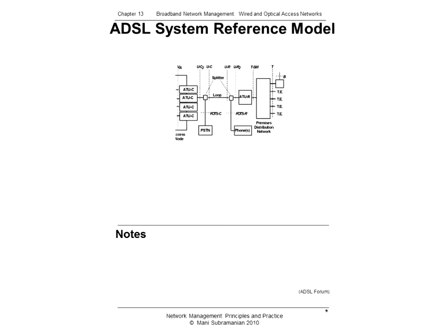Now this figure shows the ADSL system reference model. Here we have additional components that we call splitters at the central office and the customer premises, which separate low frequency telephony from voice, video and digital data.